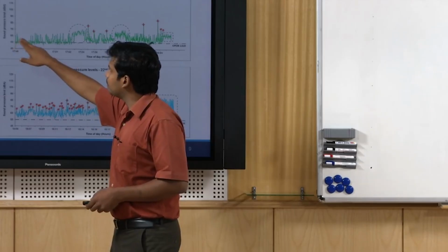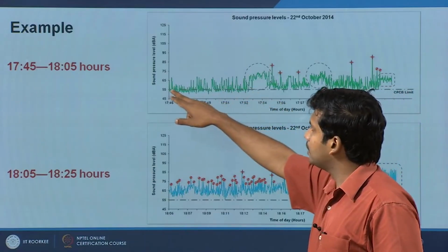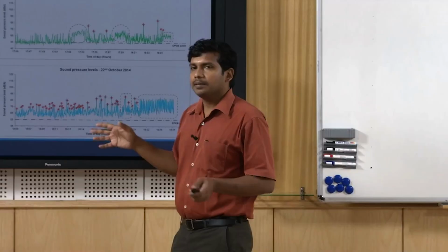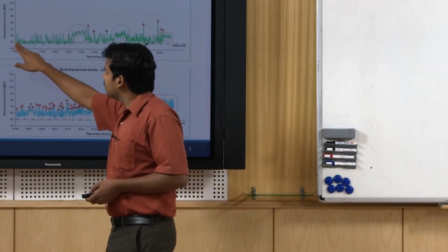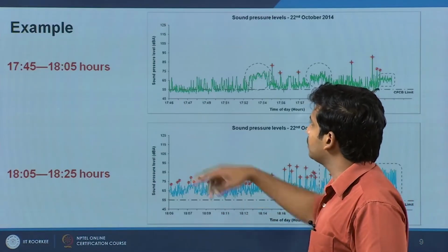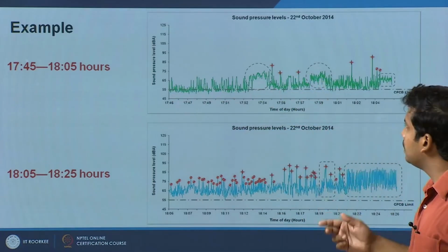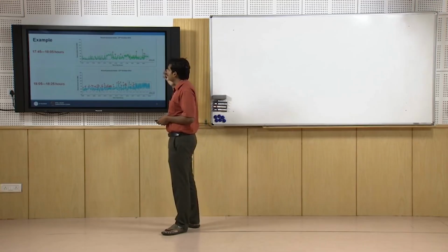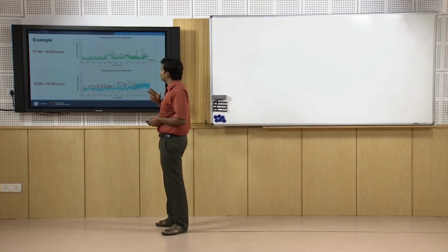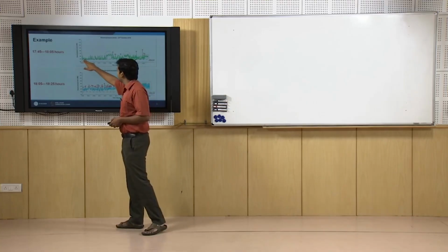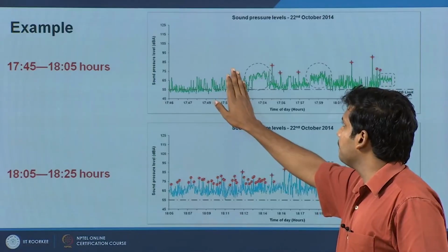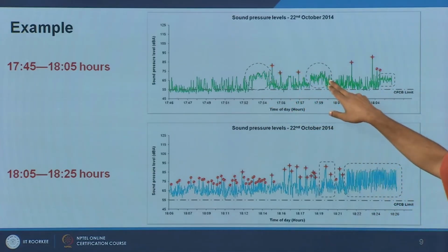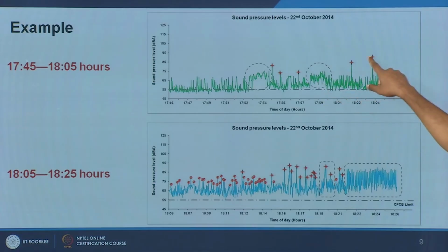What we find here is that the sound pressure level varies around 55 decibels dBA. Typically this is a suburban, residential area, so there are not many extensive noise sources. It is around 55 decibels dBA. This is the CPCB, Central Pollution Control Board limit. I will show you the desirable limits, or permissible limits, that they have given. It is the CPCB limit here. Around here there is a slight increase. There are certain high intensity sounds, certain continuously increasing sounds. I have highlighted some of them.